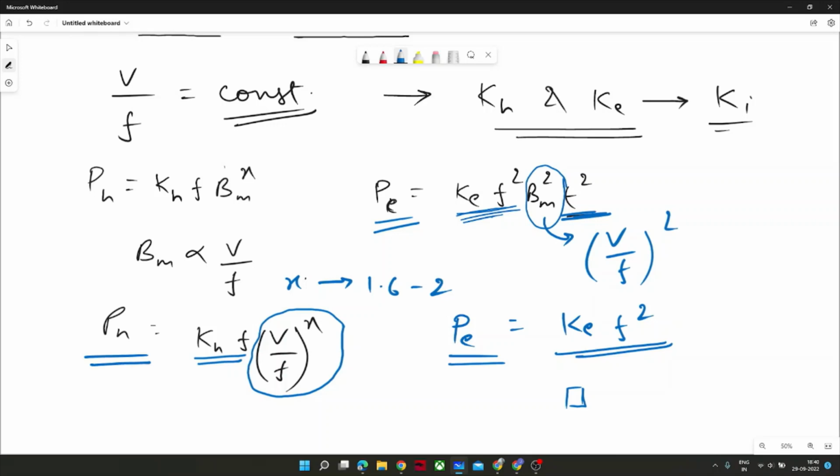Do you know how much lamination thickness we generally use for silicon steel in modern days? Yeah, you are quite close: around 0.35 mm. 0.35 is very common. That is known as material M235 or M19 as well. You can easily get it in India.